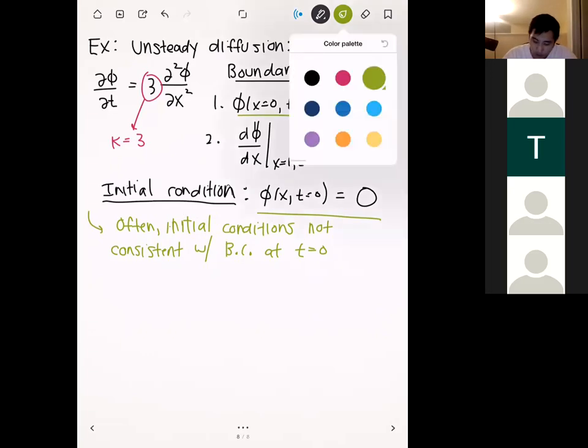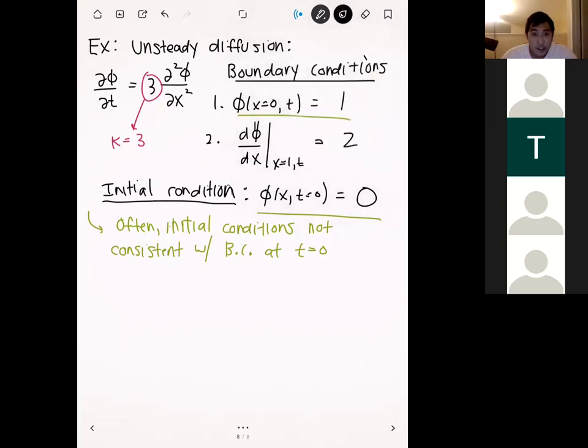All right, in order to solve this, we also need to specify values for our time step size and our grid size. For the time step size, let's use a time step size of 0.1 seconds. This tells us that each solution that we solve is going to be separated by 0.1 seconds in time.